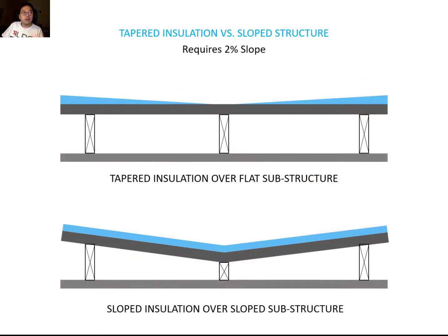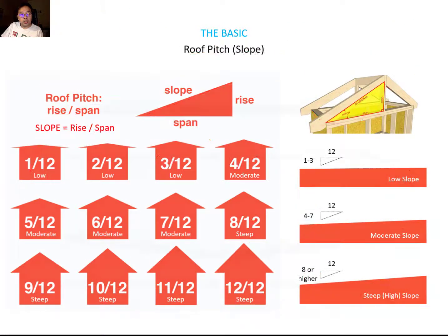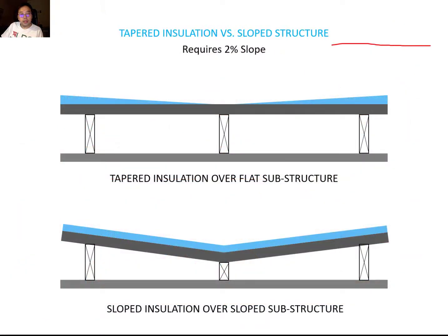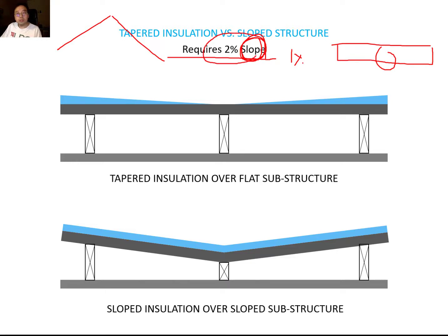Now we can consider how you can design the flat roof. So this is all sloped roof here, right? But with totally flat roof design rather than these types of gable roof, even when you're designing a flat roof, you should consider the slope. It is usually asked to have a 2% slope, but someone said 1% slope is okay, but I highly recommend the 2% slope because I will explain it a little bit later.